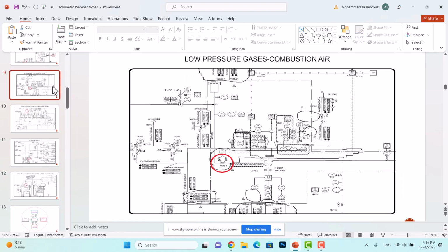Then in that table, we mentioned the Venturi type. In this example, those process units or petrochemicals which have fire heaters have, inside the package of the fire heater, an ID fan or FD fan, forced fans or induced fans, and the function of these forced fans or the combustion air blower is to blow air to the fire heaters for combustion purposes.